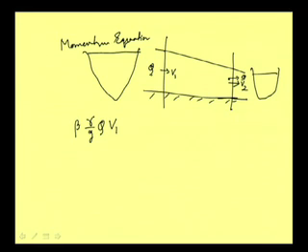Do not confuse this with an intensity property or something like that. Beta is the momentum coefficient. So, this is the momentum at that point, and then the momentum at this point will be beta 2 into gamma by g and Q into v2, since the momentum coefficient can be different here.